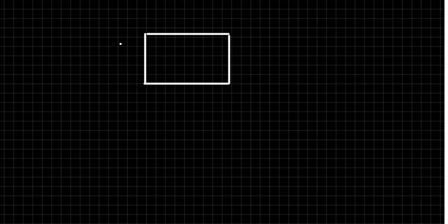Shift, right? So it should be X, X, X, followed by 1, 1, X, X, and so on. You got it? This should be the output. But without using the inbuilt reg, without storing anything, you have to go for this, using structural design. That means first you implement a D flip flop and use that as an instance for the next module.